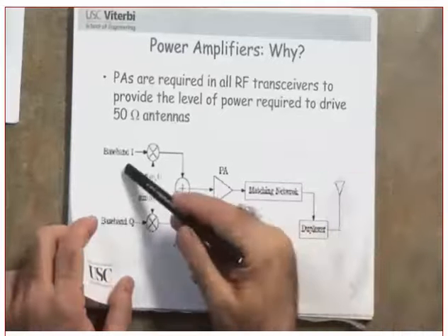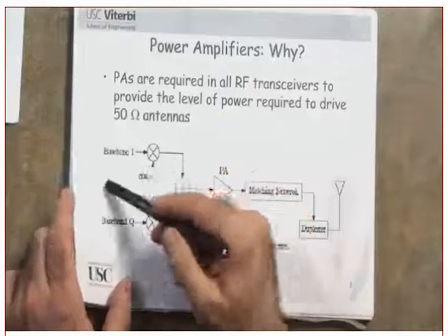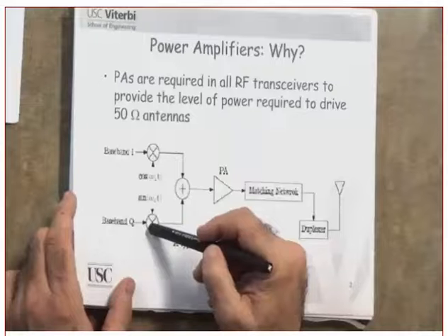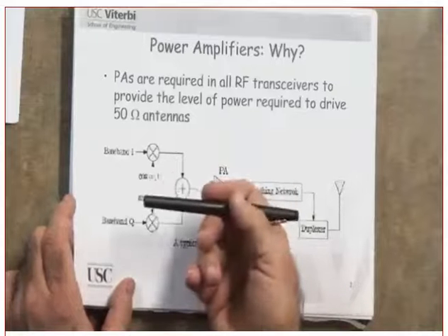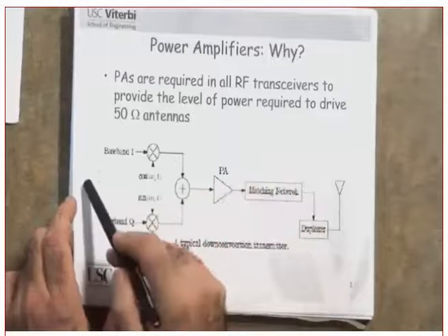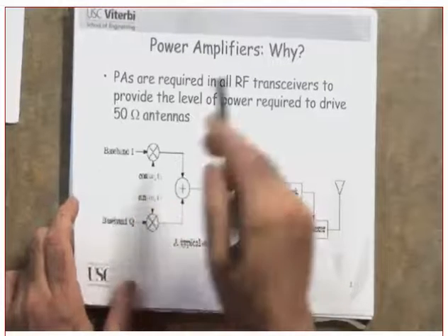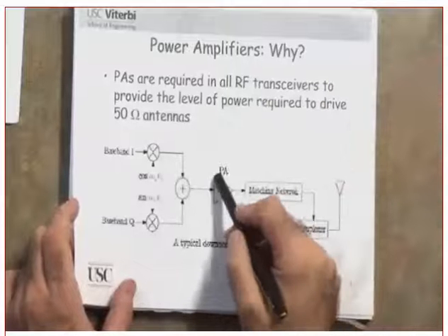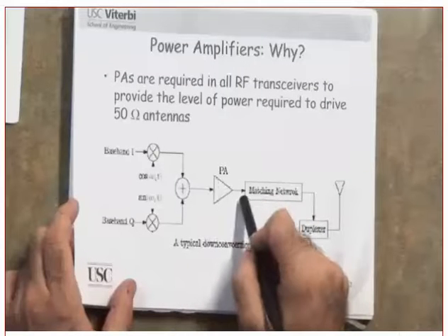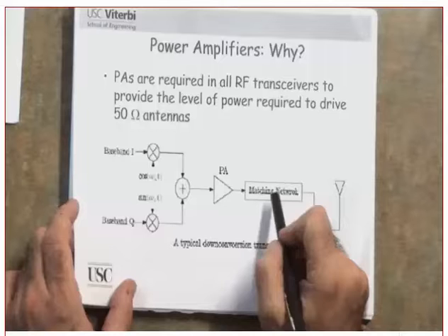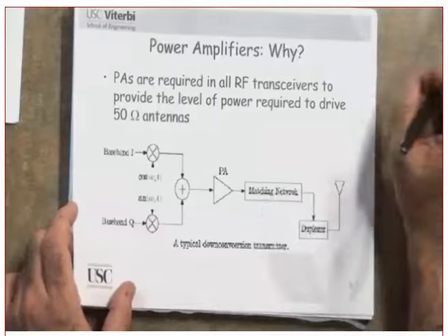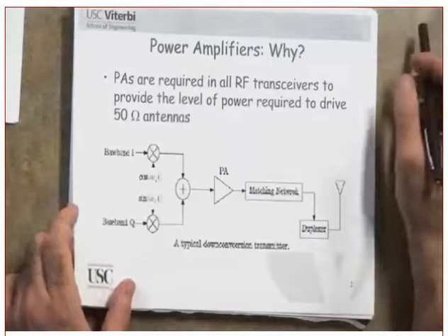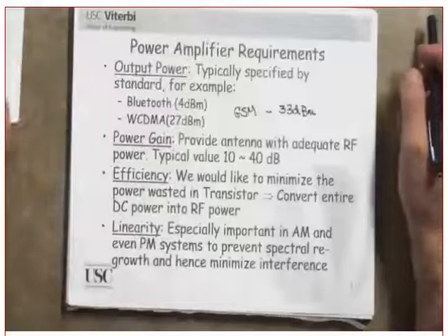range. This is, again, the modulation process, the IQ. By the way, in here, it shows that the modulation is taking place in one step. Could it go into multiple steps? In other words, could it go into IF and then the RF and so on? This is just a diagram here. And this is the power amplifier sitting here. We saw that we need to connect it to a matching network to try to reduce the amount of power being reflected. Clear? The amount of power being reflected means that you are going to lose it.